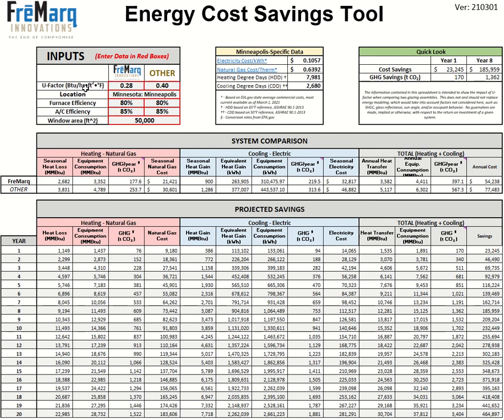After the required information is entered, the remaining cells will populate with information. Let's start by taking a look at the system comparison section. The values provided here show a direct comparison between the two systems being evaluated on an annual basis. The cells under the red heading show the energy consumption and greenhouse gas production due to heating, and the cells under the blue heading show the energy consumption and greenhouse gas production due to cooling. The cells under the gray heading at the right sum the heating and cooling energy consumption and greenhouse gas production and converts the energy use to a dollar value.